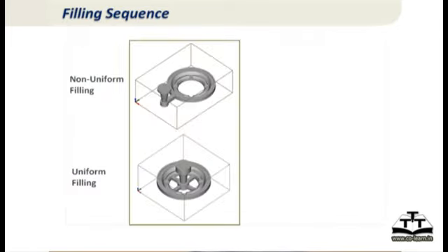Now let us look at the filling uniformity. That is the last criterion in good filling. If you remember, we talked about complete filling, then smooth filling and uniform filling. So in uniform filling, if you look at the first example here, some kind of a wheel casting, if you put the sprue on one end and the gate at one end, by the time the metal flows around the casting and goes to the other side, the temperature is falling, it's picking up slag and perhaps air also, and you may not get uniform properties in that.